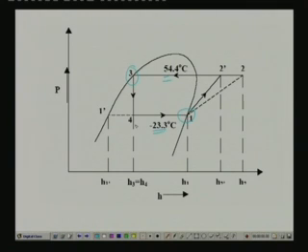Once you say that it is saturated vapor and temperature is specified, we can immediately locate the point and find out the enthalpy H1, the specific volume, the entropy, and all the properties can be obtained at this point. Similarly, all the properties at point 3 can be obtained just from this temperature and the quality, because it is a saturated liquid. These properties also can be obtained directly from the refrigerant database, or if you have a pH chart, you can directly locate these points.